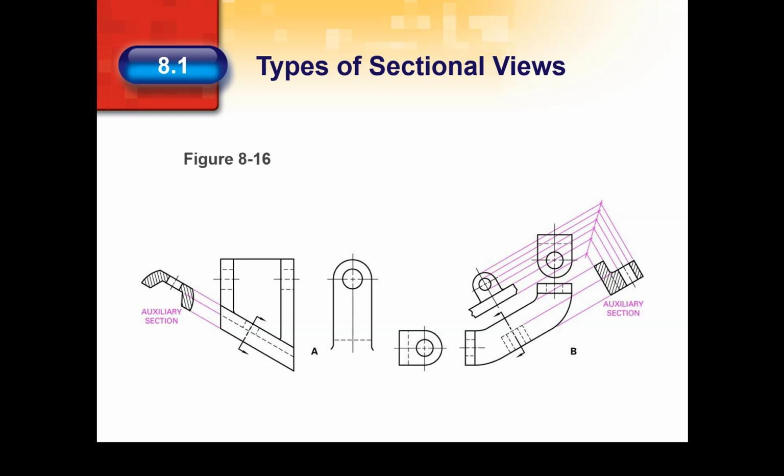On typical working drawings, only the auxiliary section as shown on the cut surface is drawn. However, if needed, other background features or parts beyond the auxiliary cutting plane may be shown. In figure 8.16b, notice that the auxiliary section contains hidden lines. It also contains 3 incomplete views.